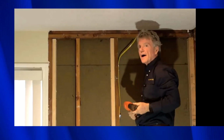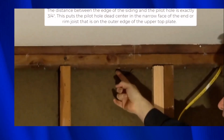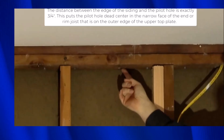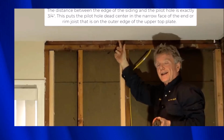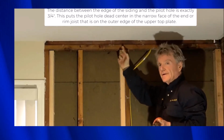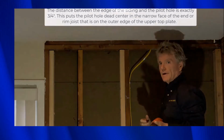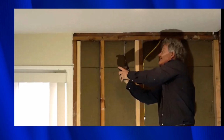Now that is a pilot hole for the lag screw. Now this is exactly 3/4 of an inch from here to here. The floor joist above is 1.5 inches. So when I drive the lag screw through, it'll go right in the center of the floor joist, which is where it belongs. Okay, there's the lag screw right here. Here's my driver.